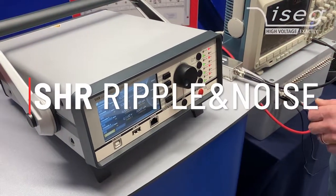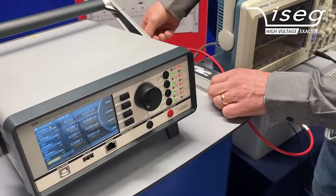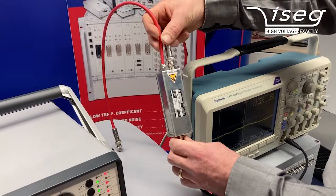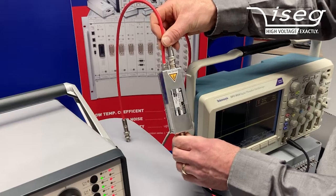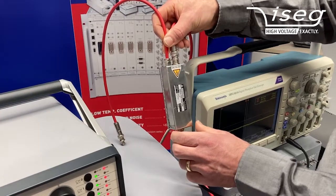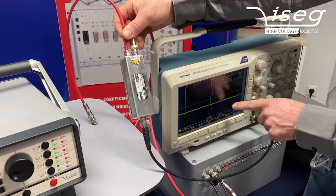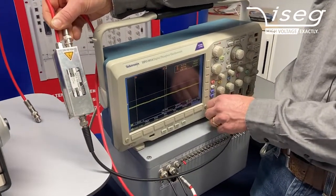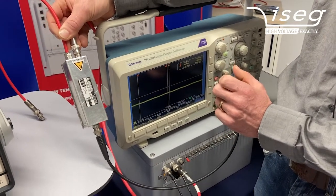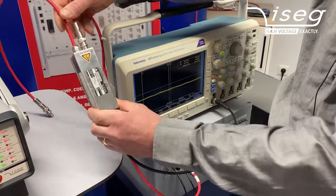Now we want to demonstrate the quality and the stability of the high voltage provided by the SHR. For this, we use here a little device. It basically consists of a high voltage capacitor that allows us to decouple the AC component from the DC component of the high voltage, so that we can display the AC component directly here on an oscilloscope. This is basically the parameter that we specify as ripple and noise, so the noise on top of the high voltage. You can see here directly.